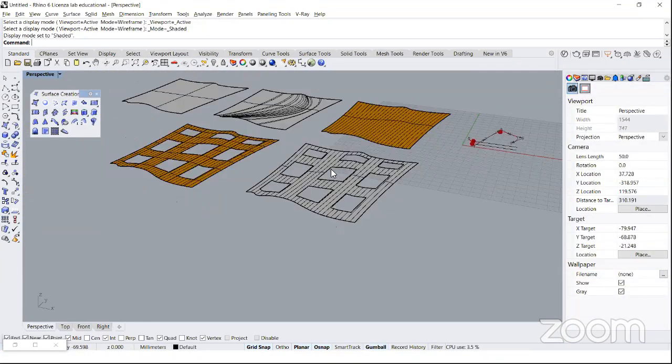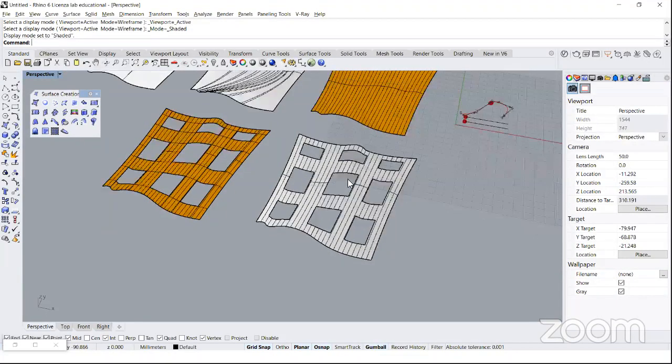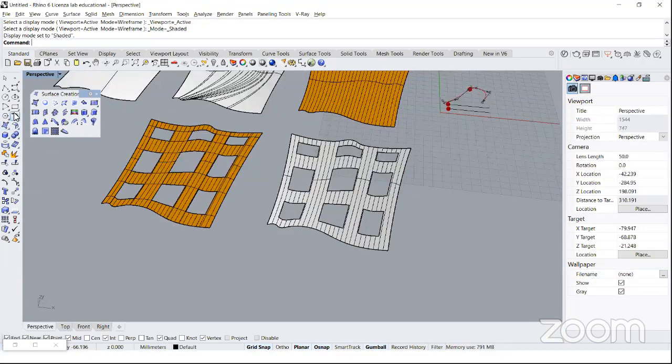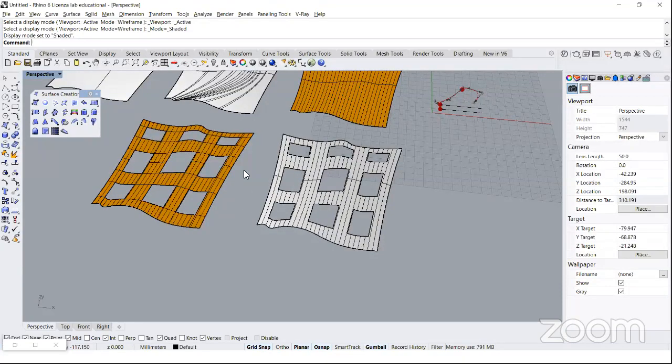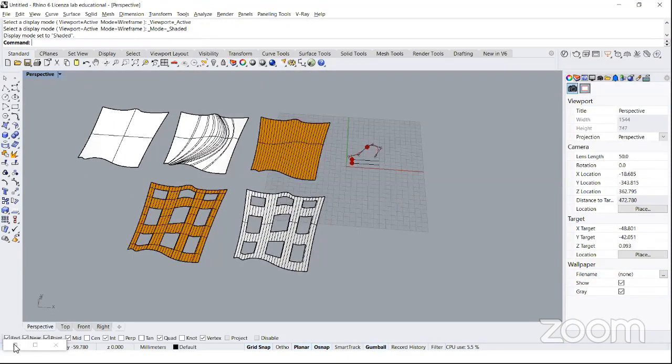But it's not just like flipping the surface, okay? It's important to do this because, just so that you know, it affects important commands like, I don't know, the UV curve creation and also the flowing on surfaces and so on. So all these commands depend on the topology of the surface. Okay, so pay attention to these details when you work with surfaces.